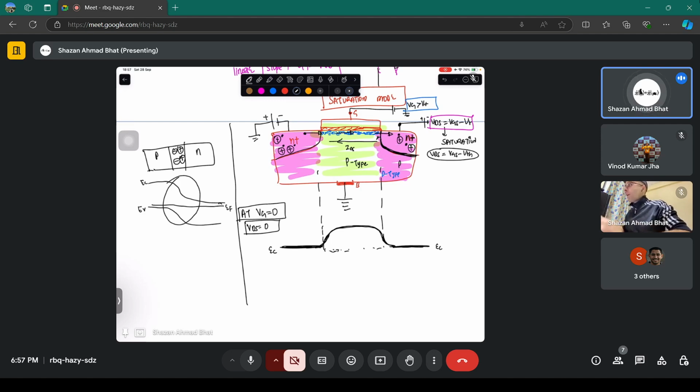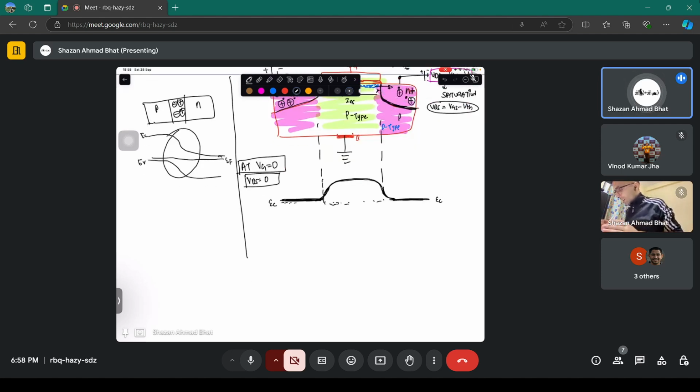It's so highly doped that the electron concentration is very huge, of the order of 10 to the power 18 or 10 to the power 20. It almost behaves like a metallic system, almost like a metal. So many electrons. It's called a degenerate semiconductor, where the Fermi level is almost touching the conduction band.